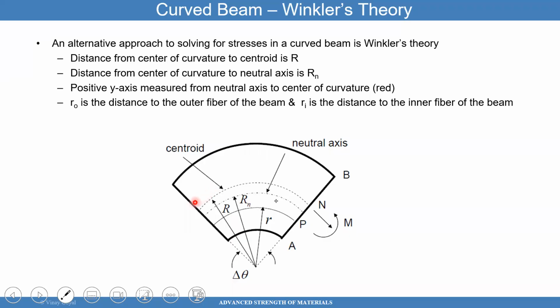Okay, so we have the centroidal axis of the curved beam, and then we have the neutral axis of the curved beam, which is right here. What is a neutral axis? The neutral axis is a location in the radial direction where, when moments are applied, there's no stress. In one of the exam problems I gave you, the principal stress was actually 0 because the location I gave you was at the neutral axis. The stresses were 0, 0, 0, so the principal stresses are 0, 0, 0. No calculations required. I asked to see if you could do it quickly.